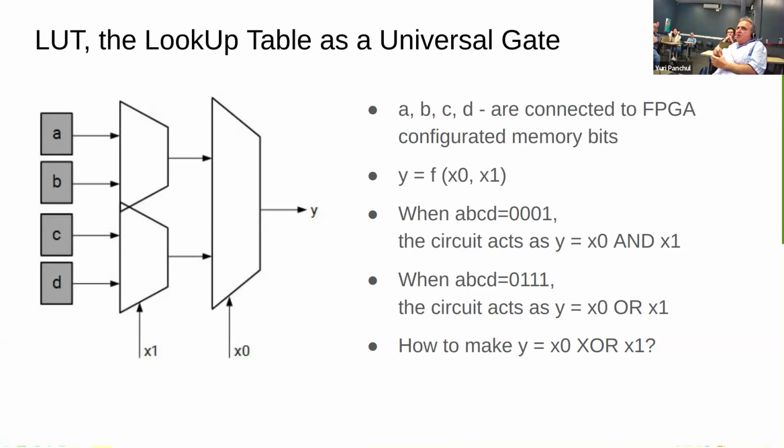But now the question is, why don't we have FPGAs in all our telephones if they're so convenient? The problem is that in order to do this, you need to spend orders of magnitude more transistors than you would with a fixed ASIC technology, where you put the design to a foundry and manufacture it there. To have the equivalent of what we have in a telephone, you need a whole big box filled with FPGAs, and such a big box exists.